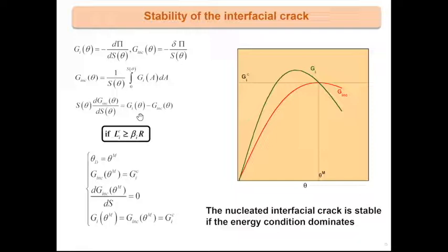Here you have the energy release rate, and here this is the incremental energy release rate. And of course, you have a relation between those two quantities. It is very simple. The incremental energy release rate is obtained by integrating the energy release rate. And so you have a simple relationship between Griffith's energy release rate and the incremental energy release rate.